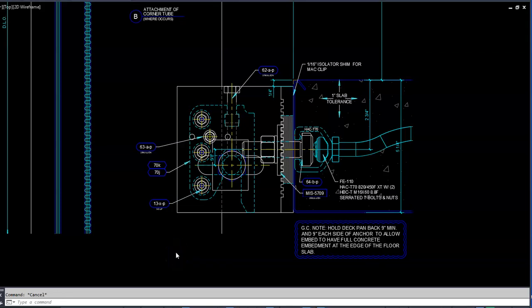So now I'm just going to demonstrate the correct way to replace these blocks into an existing drawing. The incorrect way would be to just open the library detail and do a Control-C and then try to paste it. So that would be incorrect. We don't want these blocks to be overwritten by the history of what is nested into these older files, and we have some inconsistency with block names. So that could cause some issues in the future too.